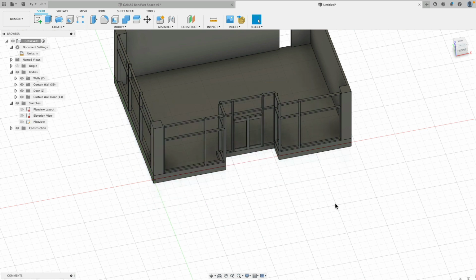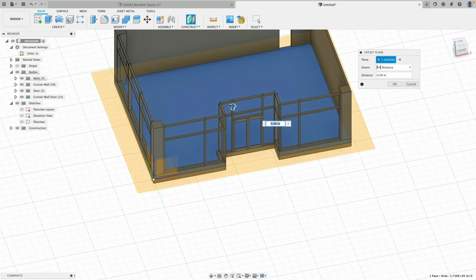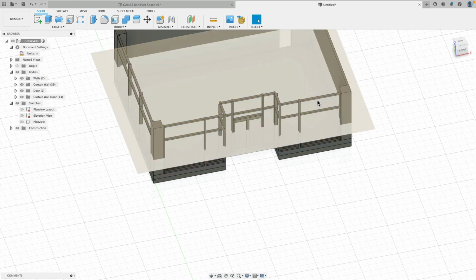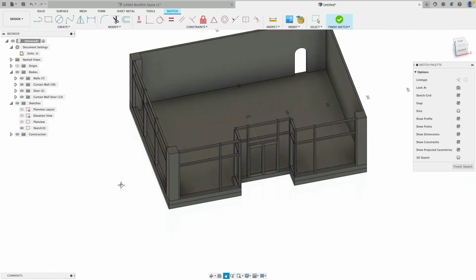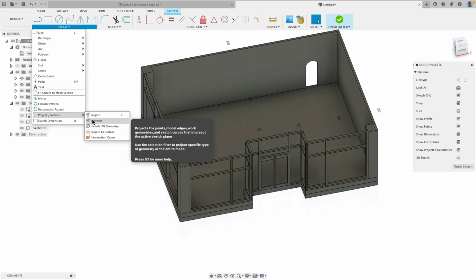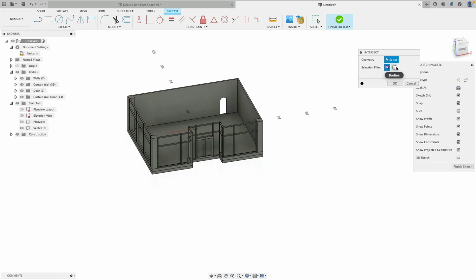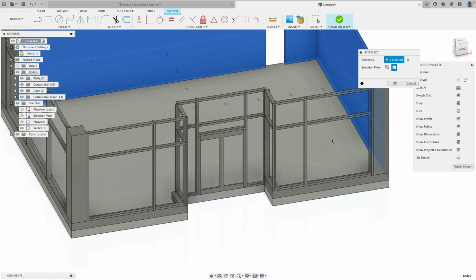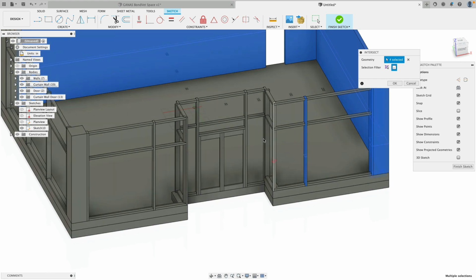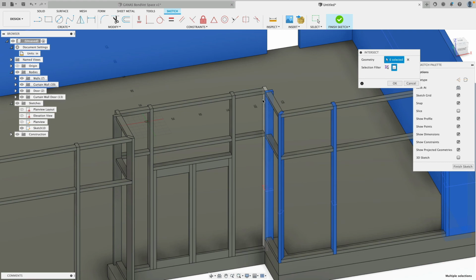So how can we create a sketch that is somewhere at a section or intersecting everything? So let's make a sketch from here, from the ground up 60 inches. We select very good, just to show you how this works. So sketch on that construction plane. And now I do not use the project. I simply use the intersect objects. And here, click. And I click on all the vertical elements. And there you see, it will then create everything for me.